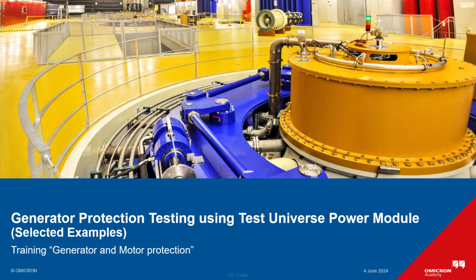In this video we will talk about generator protection testing using the Test Universe Power Module, and we will explore how the Advanced Power Module test can be effectively used to perform generator protection testing. We will walk through the testing of generator protective functions including overcurrent, under excitation and reverse power protection. We will demonstrate how to use power view, power shots and power ramps to verify both operation and trip times, ensuring that each relay responds correctly under simulated fault conditions.